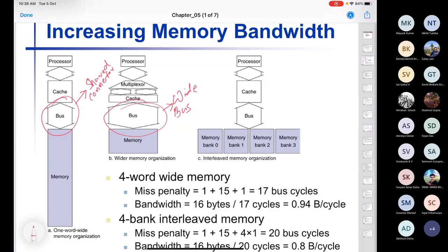Now these blocks are so large that even the memory buses cannot read them in 1 clock cycle. For example, if a block is an extremely large block, say 1 megabyte, probably no memory bus has a 1 megabyte width. So in that case, it will be broken up into a certain number of collection of words, and then it will be read. But still it is better than reading in 1 word at a time. Then 1 megabyte reading will take a lot of clock cycles. Instead, if it is reading in 4 bytes at a time, it will take 1/4 the amount of clock cycles.